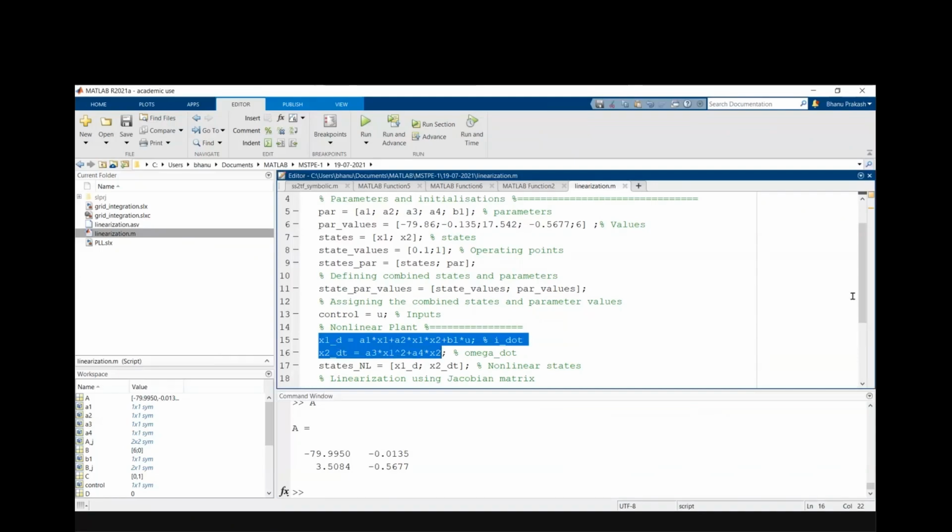Yeah, if it is fourth order, you have to convert into first order. Are you saying four state variables, or fourth order means x1 derivative, I mean x1 triple dot, x1 four dots? If you have that fourth order, then you have to expand it and make it a first order system like this. Once you get the first order system, okay, four state variables. Yes, sir, any number of state variables.